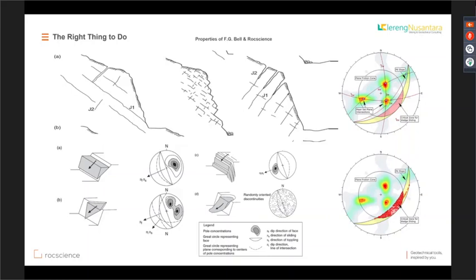In this model, I've applied an anisotropic material model to simulate weaker ubiquitous joints that have the potential to form a wedge or planar failure through the bore nose. The result is a factor of safety of less than 1, which simulates a sliding failure mechanism through the bore nose. These next few slides show different perspectives of the pre-failure geometry on the left and the geometry of the critical failure surface on the right.